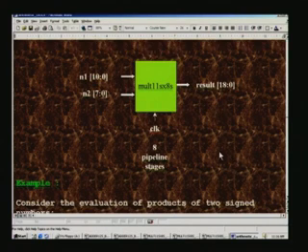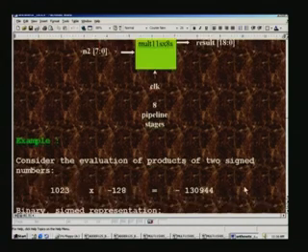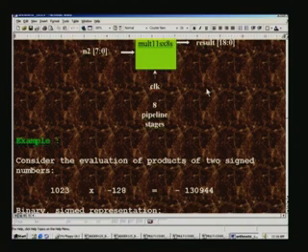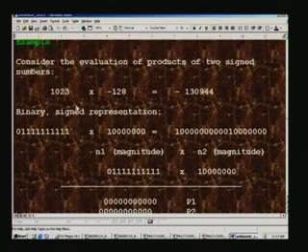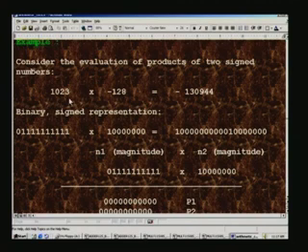And before we go into the details of the algorithm, let me mention that this multiplication is done primarily as a magnitude, and therefore first what we will do is separate out the sign from the magnitude and apply the algorithm only for the magnitude, and we can deal with the sign separately, which turns out to be a simple exclusive OR gating. And before we consider the algorithm, let us take an example. We want to evaluate the product of two numbers, let us say 1023 and minus 128.